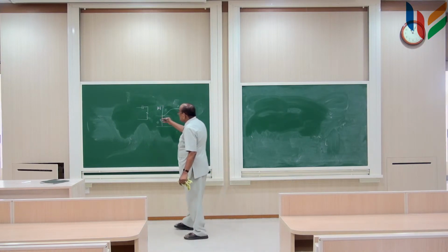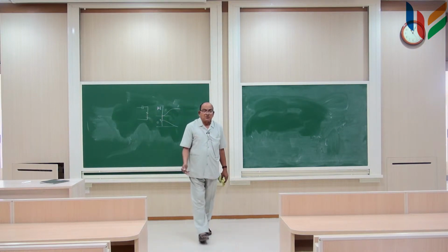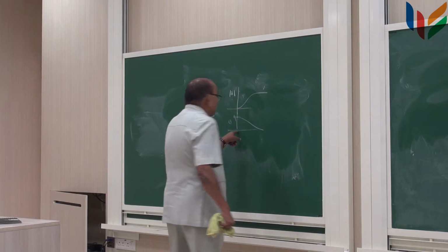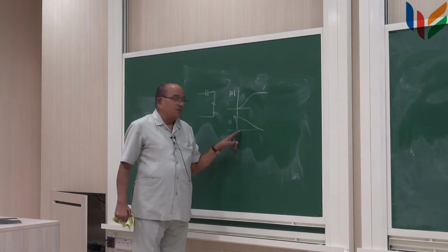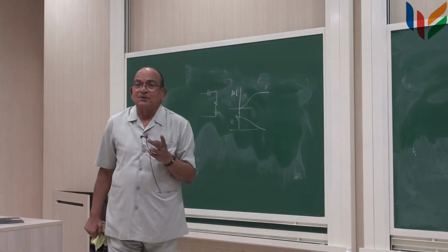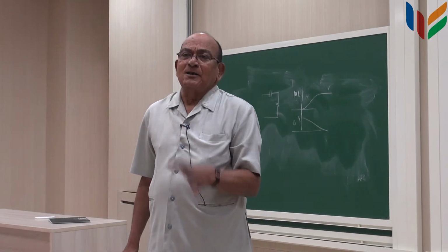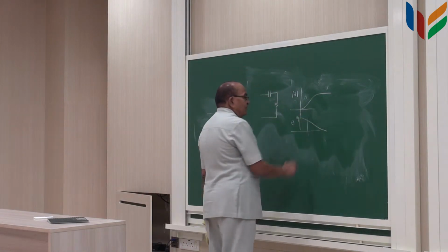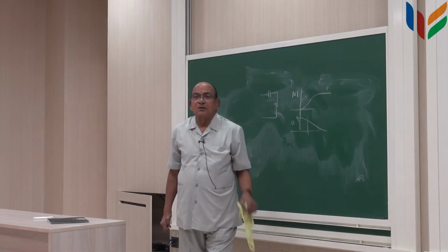So, if you put two such networks, hopefully you get 180 degrees phase shift, provided you are operating at this frequency, 0 frequency. If you go slightly more frequency, this is no longer pi by 2. So, if you put two of them in cascade, the phase shift you will get will not be 180 degrees, right. So, to really get 180 degrees phase shift, you will have to operate it somewhere here, but one section will not do, you need to have more than 2 sections.